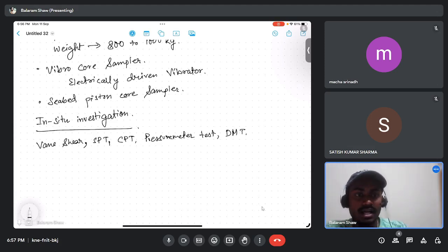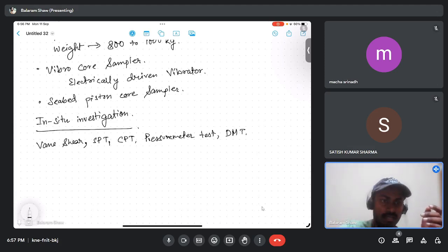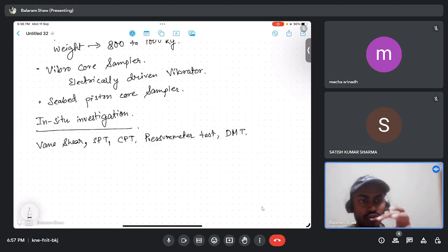Then for the CPT, two widely followed methods are used. First, the cone is penetrated into the seabed by means of a wheel driven assembly, which is first lowered to the seabed from the vessel, and upon rotation of the unit, the CPT rod is pushed into the seabed. This one is the wheel assembly.